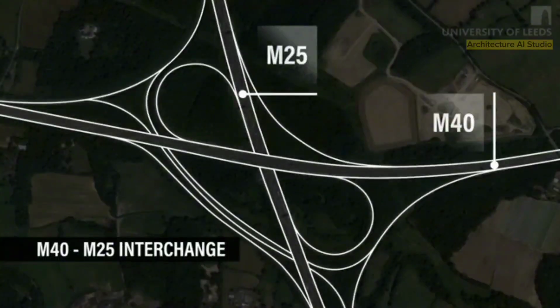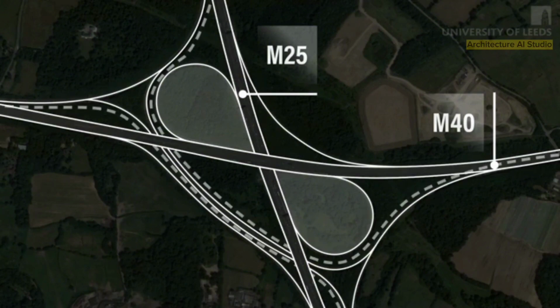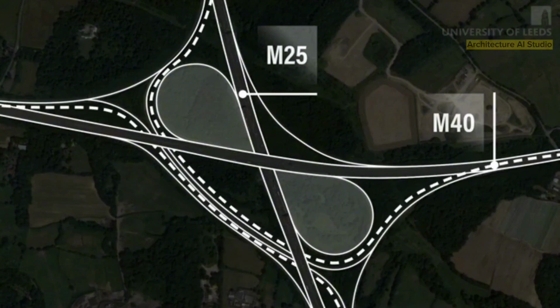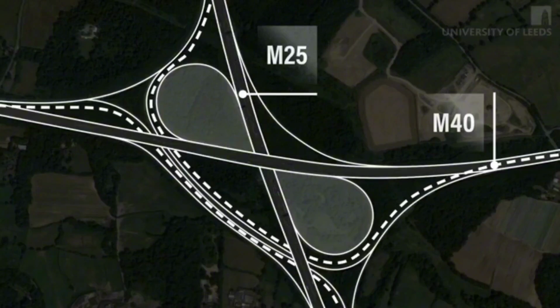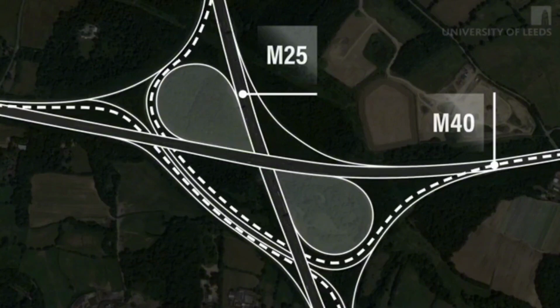This is the M40-M25 interchange. Note that in this junction design, one cloverleaf-shaped loop is provided for the north and southbound traffic, each to turn right onto the M25. But the east and westbound vehicles will follow a straighter link in order to make the right turn. Both the links are located in the third quadrant. Land use restriction in the first and third quadrants is likely the reason for this layout.